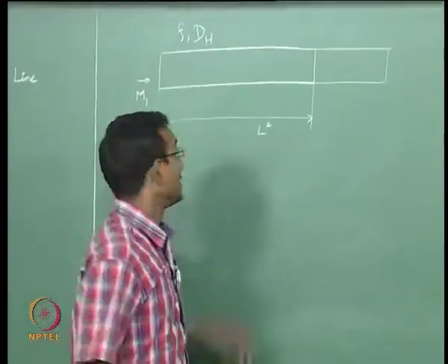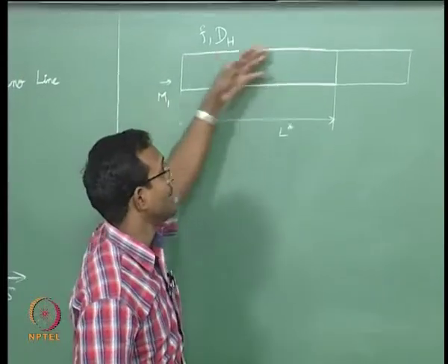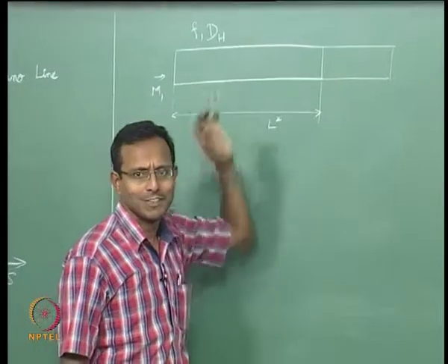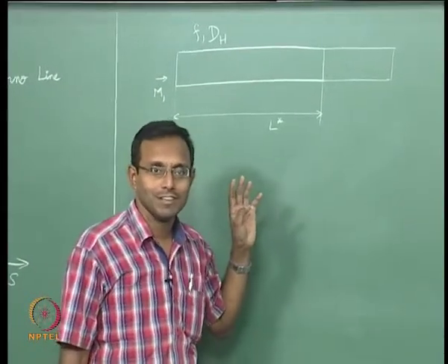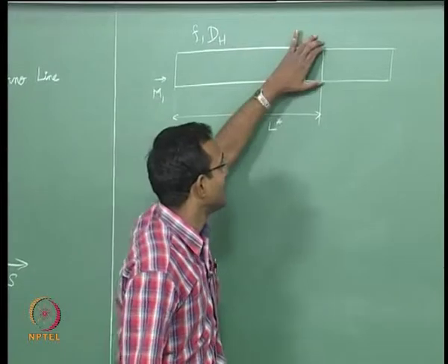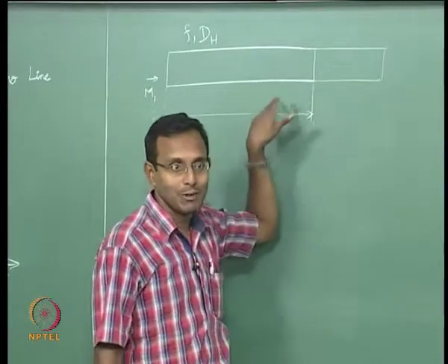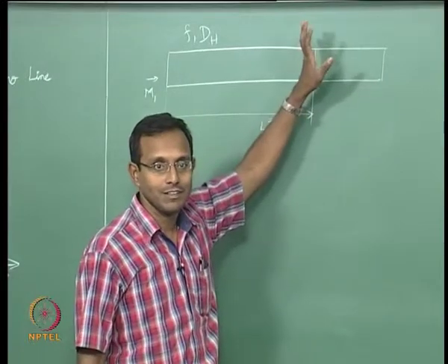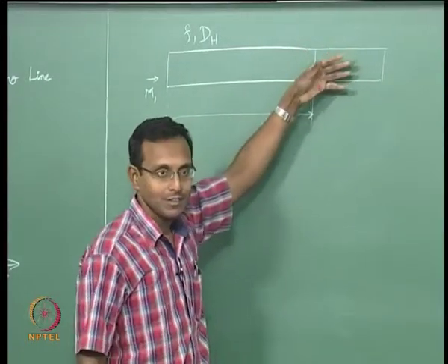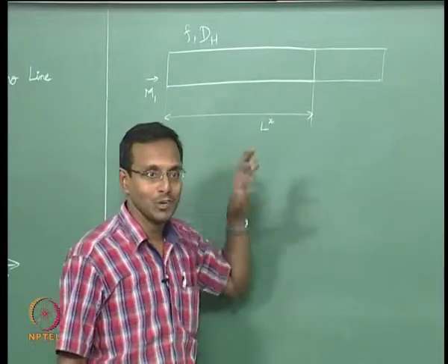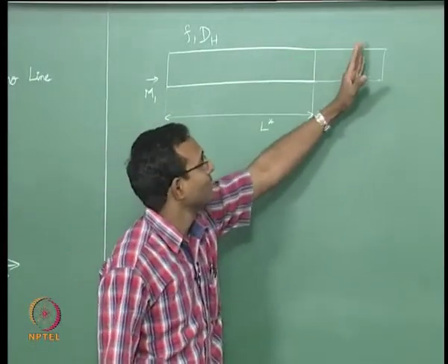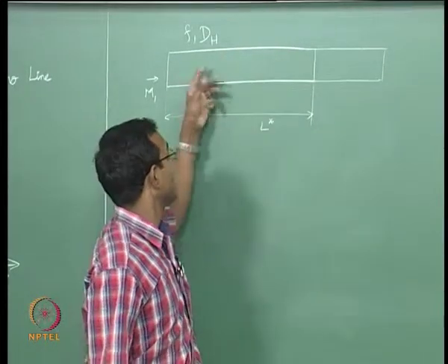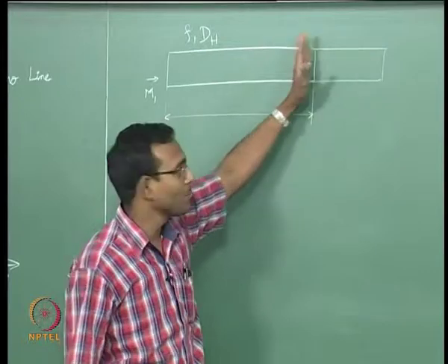Okay. If it is subsonic flow and I am sending compression waves inside, what will happen? Compression waves always travel at speed of sound. What should happen? Say I just introduced this length L, all the same it was not there, I just added this small tube extra on this. Now the flow has to go through this, from that time t equal to 0 when I added this, there is going to be a set of compression waves that is trying to go in. What will happen? They are going to go faster than this flow. They will keep on going in.